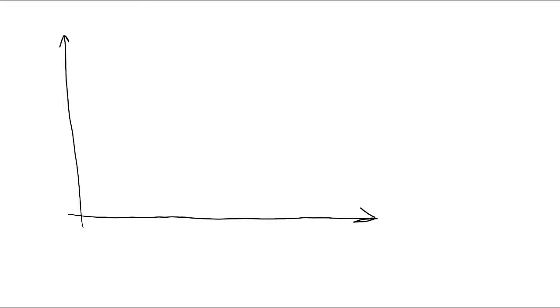In order to be able to write an actual number of degrees to our servos for their angles, we need to do a little bit of algebra. Let me show you what I mean on this plot. I'm going to draw an x-axis and a y-axis. I want to be able to input a number of degrees for an angle, and I want to output the right compare value. For servo 1, the most clockwise angle is defined as 0 degrees, and the most counterclockwise angle we're defining as 180 degrees.